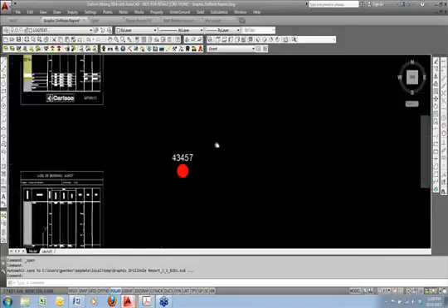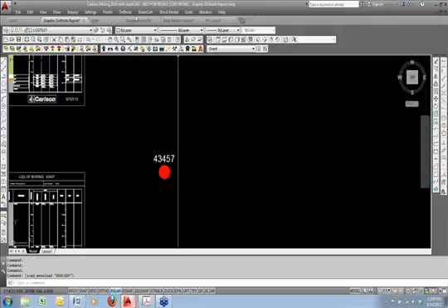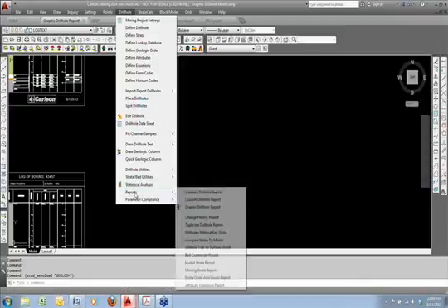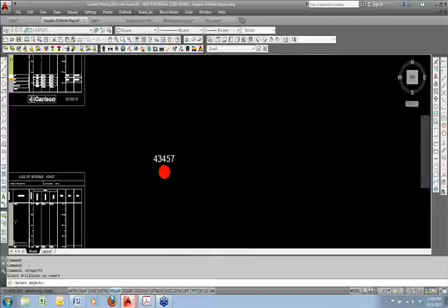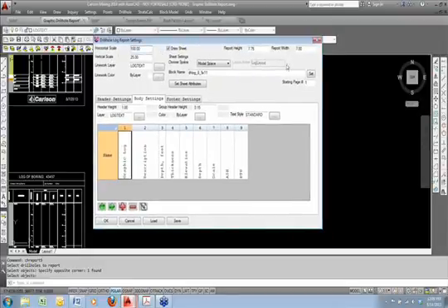In this drawing, I just have one drill hole, and we'll report that out in a borehole log. So I will switch over to the geology module. These new reports are found under drill hole, down in the reports section. I'll run the graphic drill hole report, brand new for 2014. Select the drill holes. You can pick more than one. I'll just grab this one in this drawing. Hit enter, and you've got options for the sheet size.